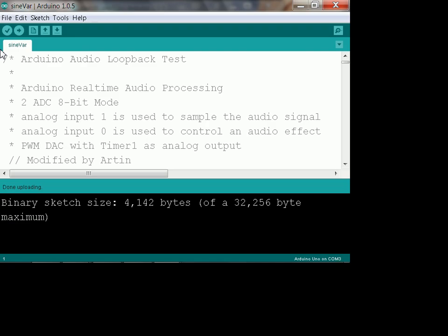Well, if you don't have a digital to analog converter, you can build one using a ladder of resistors known as the R-2R ladder. What this will do is it'll take a digital word and it'll take the different bits and it'll weight the voltage for each bit by an integral power of 2 depending upon the position of the bit, just as though you were in what's known as positional notation. And that'll work good, but it takes a lot of space and it's not a particularly good DAC.